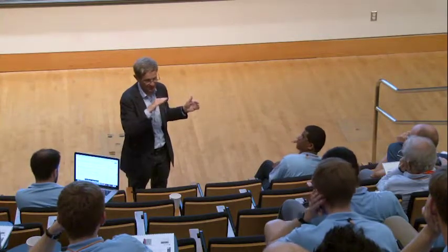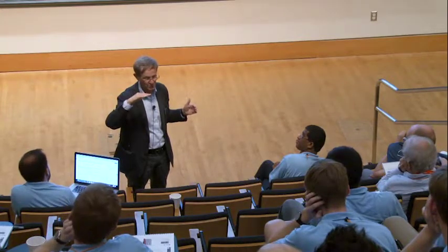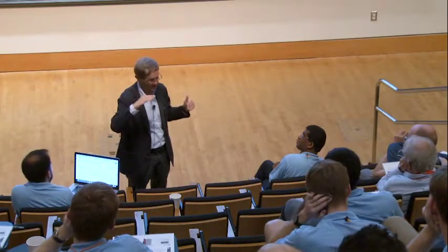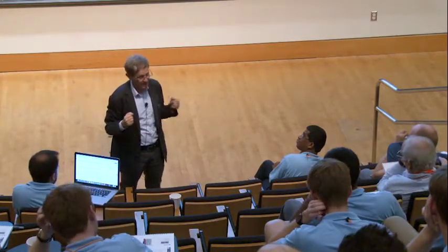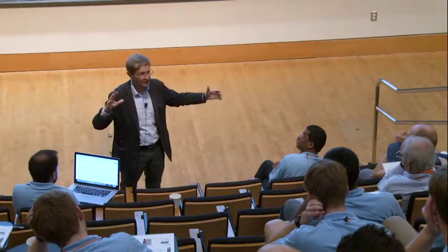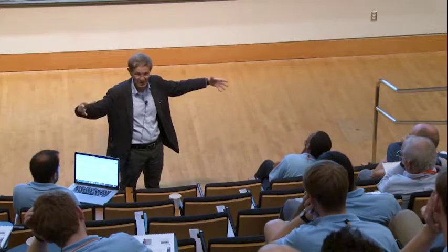This goes in the subsonic regime. As you go supersonic, this goes to Mach number to the power 3. But in the beginning, Mach to the power 8. This is why these engines, the engines which have a very high bypass ratio, produce much lower velocities at the exhaust. You have a very big mass flow rate, a small velocity, and so the noise is much lower. So the modern aircraft have very little jet noise. So most of the noise comes from the machinery, the turbo machinery.